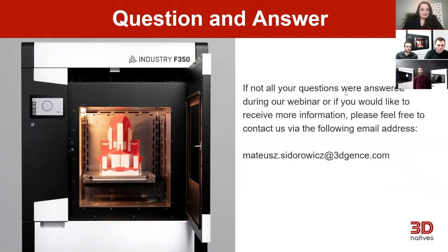So PEKK overall would crystallize somewhat more slowly, and most applications do not call for a strictly recrystallized part, while PEEK actually is more sought after in its higher crystallinity. Well, yeah, that's one difference. But the material properties vary. I mean, tensile strength is different. It depends on how the material is printed, because you can print it amorphous, and you can then recrystallize it.